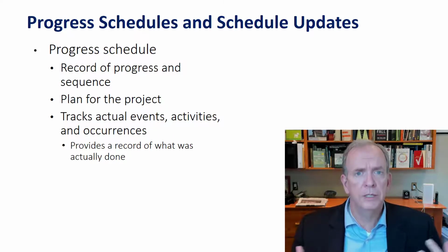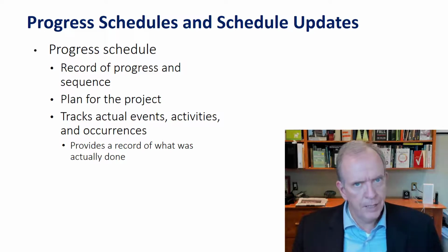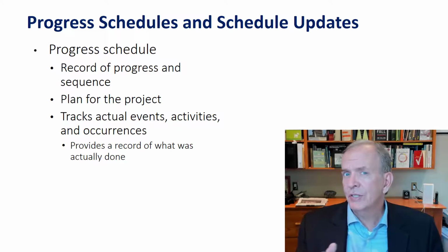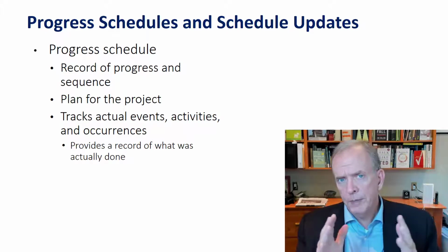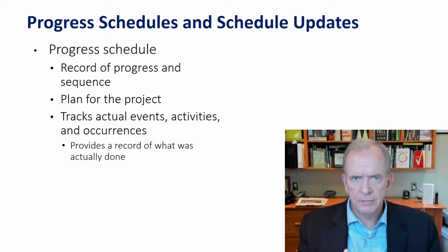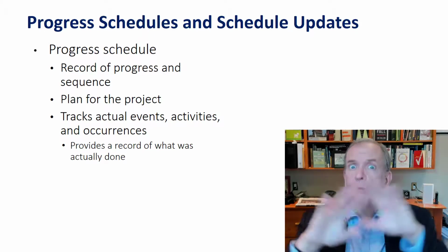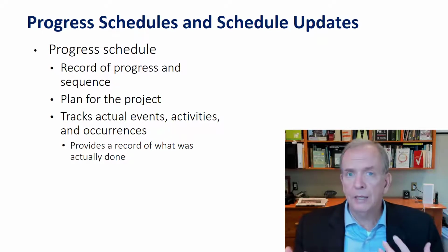I've written a whole book on this particular area because it's one of the most important areas in construction, at least in my mind. And so you develop a schedule, that's the plan. And then you update the schedule to see how you are matching against the plan. And if you start to go a little bit out, you want to know, why are you going out? Is it something you caused? Is it something the client caused? This gets into another whole area called delay analysis. But more importantly, if you're starting to go out, you want to replan the work so you can get yourself back on track and you can fix the schedule.